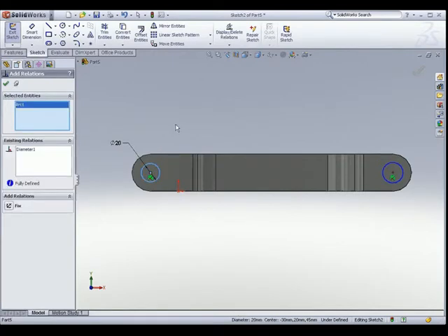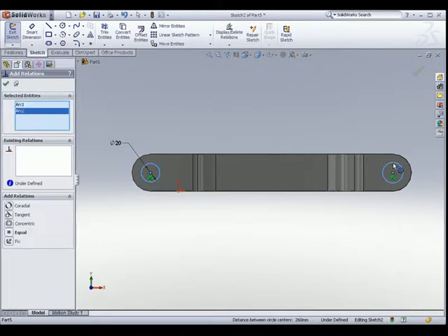dimensions. We can also add relationships between different sketches. So let's take for example, if I select these two circles, you notice there are different relations that I can create for these two sketches, such as making them tangent or concentric, or simply making them of equal diameter. So just click on equal. You notice this little green icon will show you that they are equal. Hit OK, and there you go. The sketches have turned black in color.